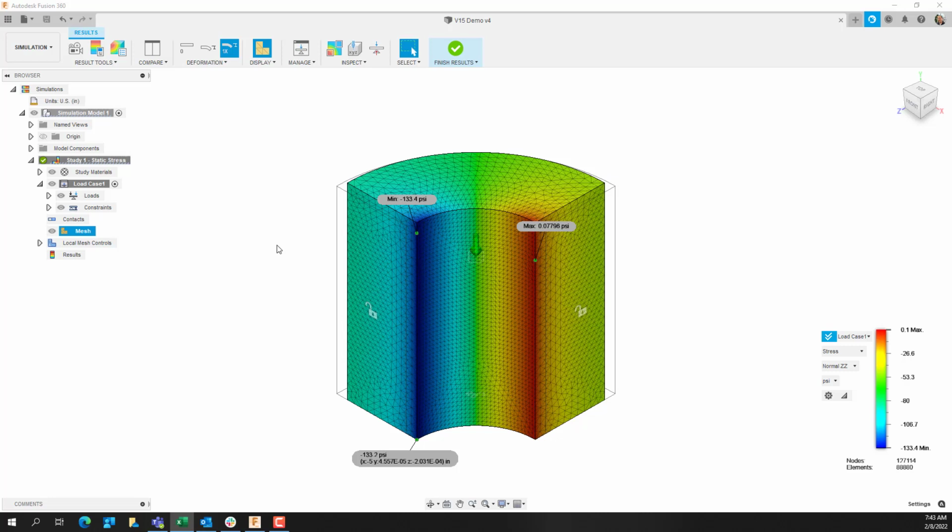But in a lot of cases, we don't have those hand calcs available. Either it's really hard to do or just haven't gotten around to it yet. And in those cases, if you have two different meshes and two different results, then it's really hard to tell, right? You might not know which one is actually closer to the truth. And so that's why I would say at least three different meshes, and then hopefully by that you see a trend, right?